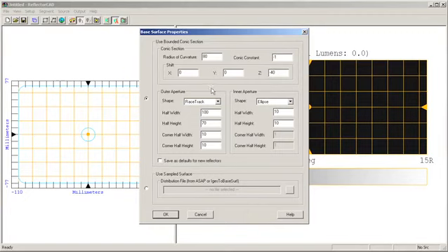Additionally, I have the ability to enter some simple output aperturing of the reflector. In this case, it's going to have a racetrack shape with these following parameters. I will also have ReflectorCAD insert a hole of approximately 20 millimeters in diameter for which I can put in a bulb. ReflectorCAD has the ability to accept other types of surfaces as well. For example, you can import surfaces from ASAP, or you can translate IGES surfaces and use those base surfaces in ReflectorCAD.